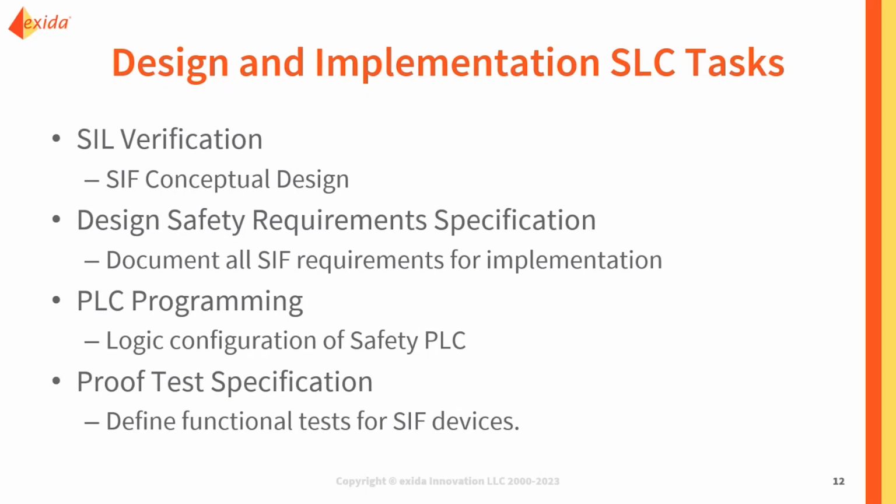The results of this should obviously be reviewed, and you might have to massage a few things, but the idea is we're providing that traceability and consistency and allowing you to use work you already did to get started on the next task. For proof test specification, we can use the proof test generator, which is going to allow you to define those functional tests for your SIF devices by providing you the manufacturer-specific steps that they would suggest for a proof test, and then allowing you to add steps to make it easy for your techs to do those tests on site.